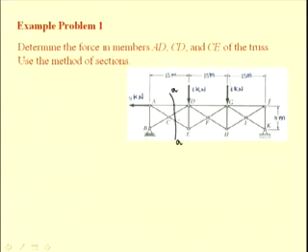But before we can proceed to do that, we have to determine the reactive force at B. So, first consider the free body diagram of the entire truss to determine the reactive force at B. So, let us consider the free body diagram of the complete truss.